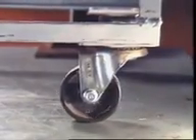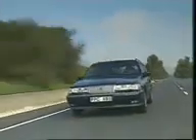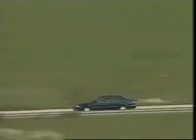The effects of positive caster can be seen in the motion of this furniture wheel. When it is acted on by a forward-moving force, its pivot point ahead of the wheel ensures the wheel always trails behind. Most cars have positive caster because it makes it easier to travel in a straight line with minimal driver action. But as positive caster increases, more and more effort is needed to turn the steering wheel. A small amount of negative caster reduces the steering effort needed at low speeds, but can make a vehicle wander at high speeds. In all cases, the manufacturer's specifications should be followed.